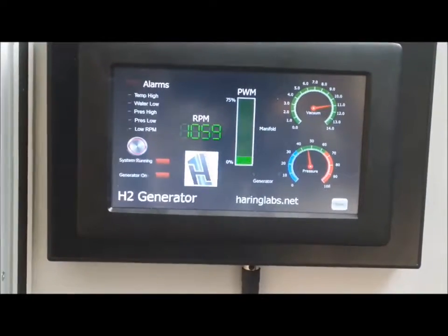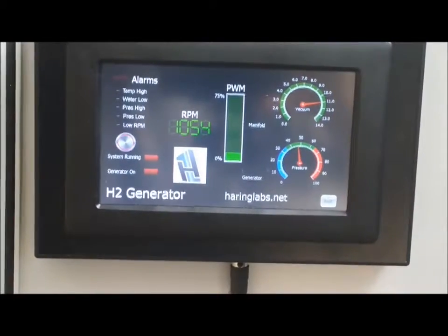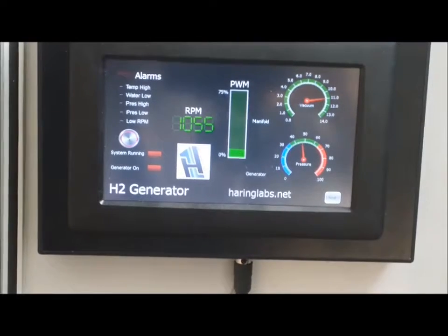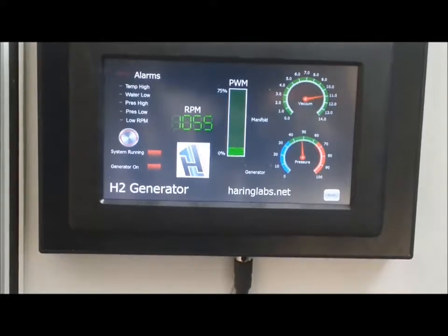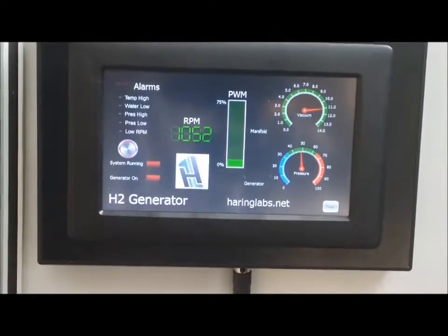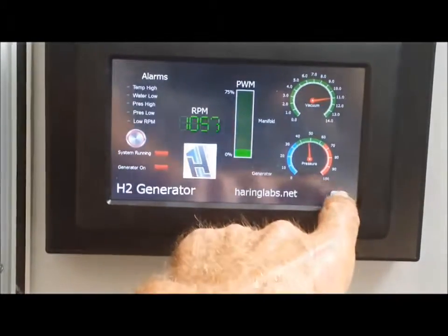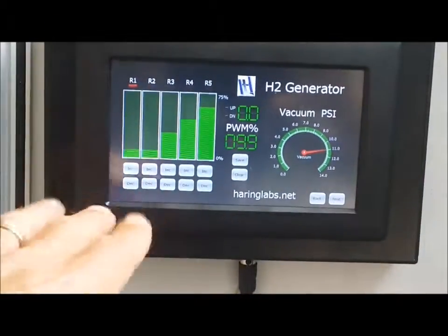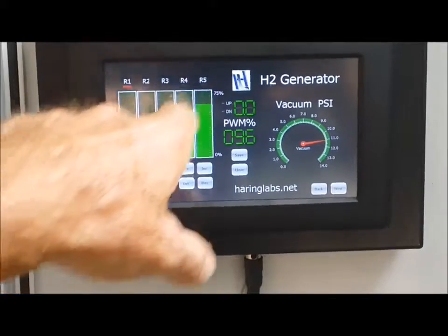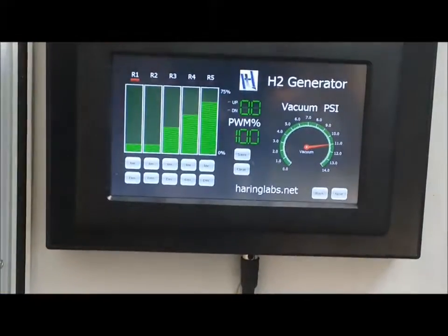So that's basically the general outline of how the system works. It's all based on engine load and how much hydrogen you want to put into your system at any one of those points. Now these scales, if you look, you set those loads, but the programming will scale it automatically up and down.